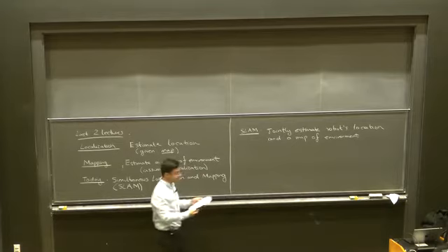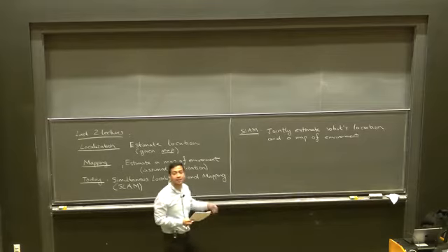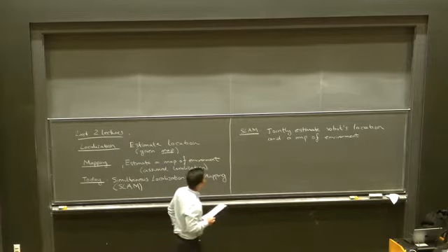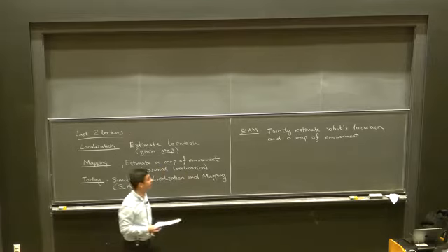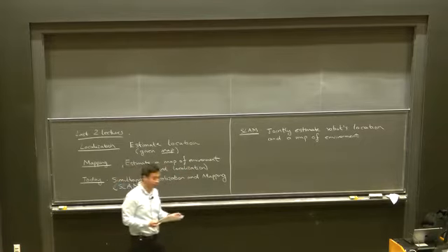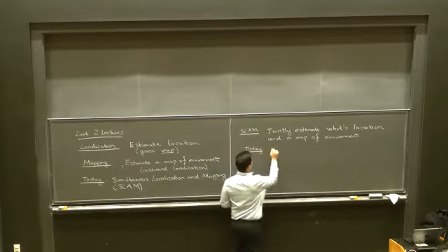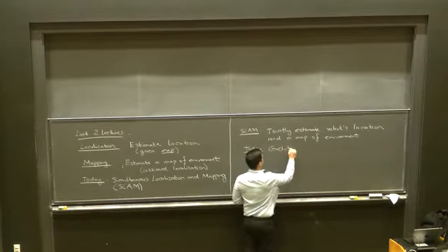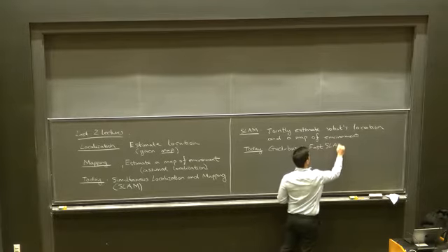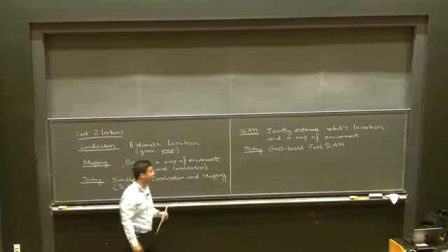Okay, and just as a quick caveat, there's a massive amount of work over multiple decades on the problem of SLAM. We're not going to do any kind of justice to this large literature. Even nowadays, people still write lots of papers on SLAM. We're going to look at just one particular approach called grid-based FastSLAM. The grid-based part comes from the fact that we're going to be looking at occupancy grids. That's going to be our map representation.